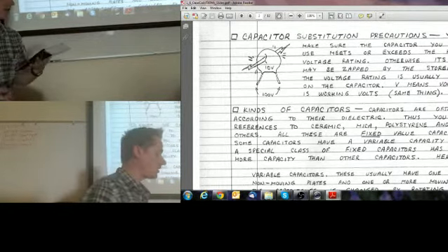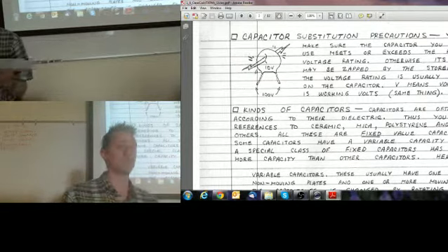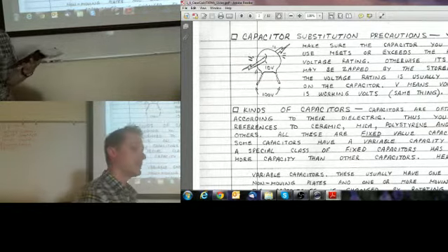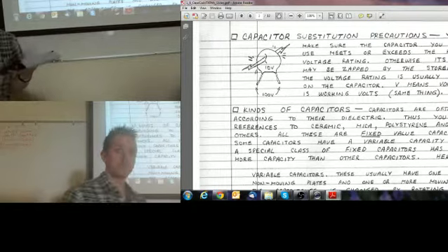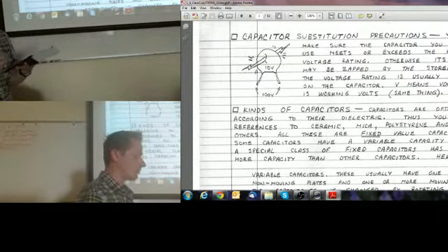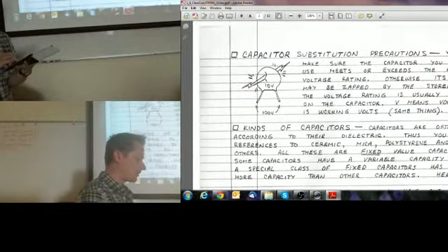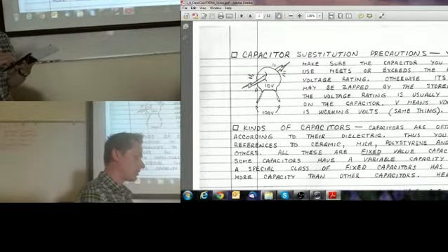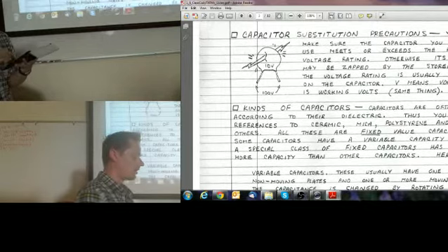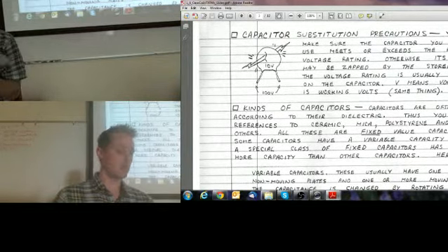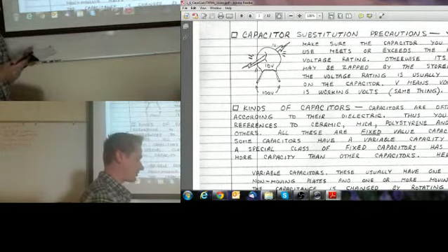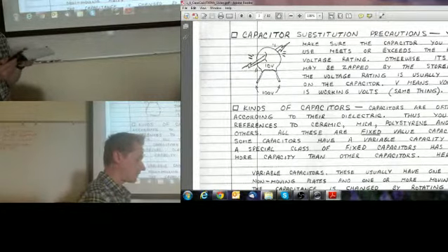So if you take a capacitor that's 2 times bigger than the one that's specified in the lab, it's going to take twice as long to charge up. But it's not going to destroy your ability to do that laboratory exercise. It's probably not going to destroy your ability to decouple your circuit or to provide a bulk decoupling capacitor in your electronic design.